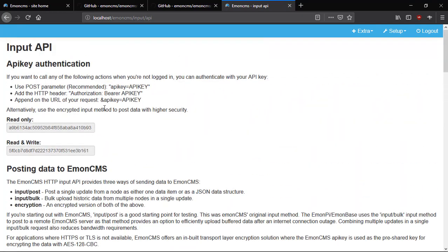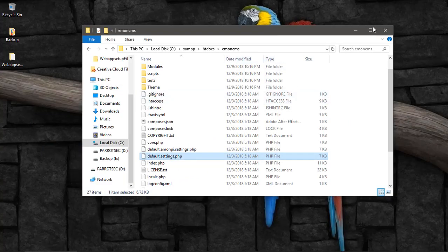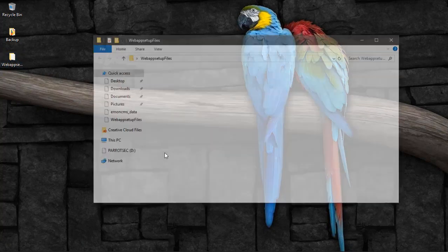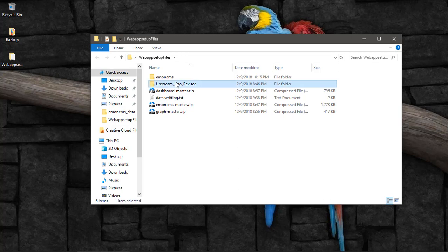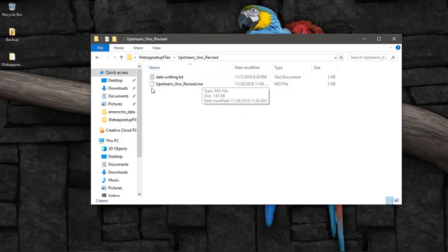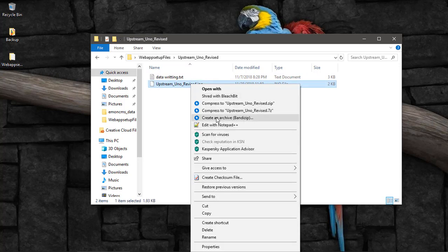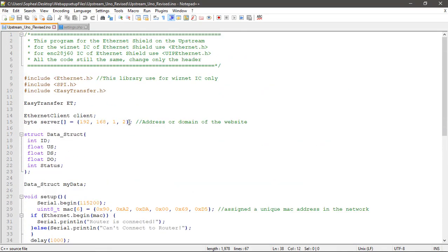Now, before moving to this point, I just want to jump out of the topic a little bit, which is going to our Arduino code for the Ethernet shield that we have written here. So this is the Arduino code for the Ethernet shield. So we try to configure this one. Include Ethernet.h. This is the library header for Ethernet, but in my comment here I just put use Wiznet IC for the Ethernet shield, use Ethernet.h. Wiznet is the W5100 or W5500, if you are using an Ethernet shield whose module chip is W5500 or